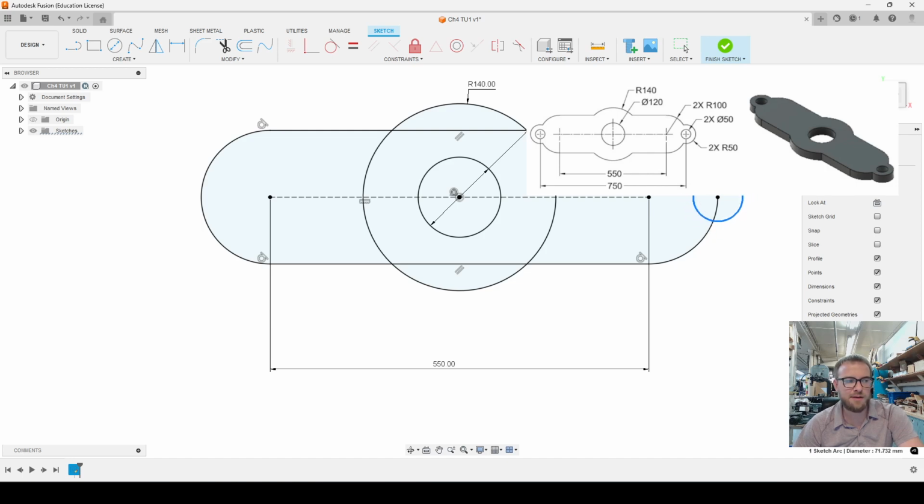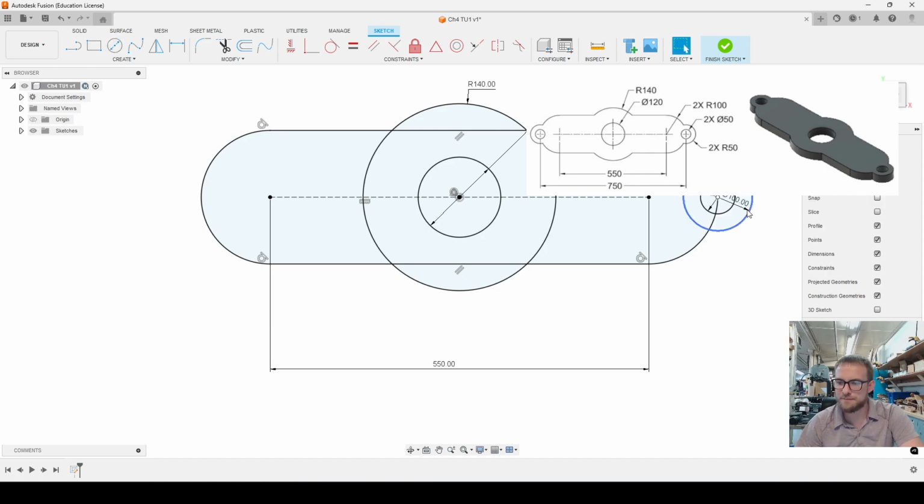It's a diameter of 50, and then there is a bigger circle around it that is a radius of 50, so a diameter of 100. Again, I'll toggle that to radius. It's kind of confusing how sometimes they give you the radius and sometimes the diameter. Fusion defaults to diameter for circles and radius for arcs, so it's kind of interesting how that works.